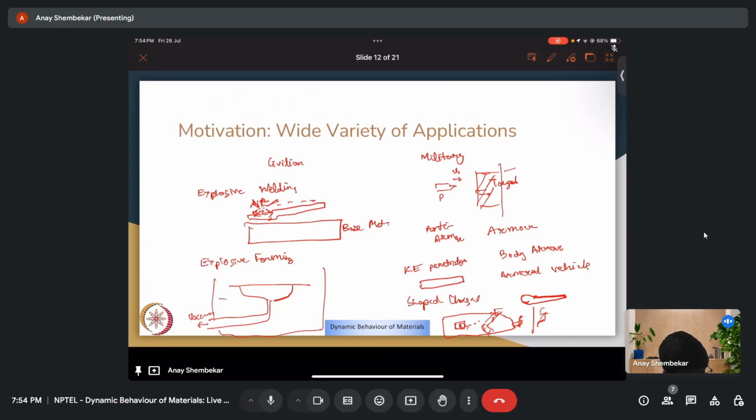You could have water or some other transfer medium for shock transfer, and then on the top, at a little distance away, you have a high energy explosive being detonated. This would create shock waves, which would transfer through the medium, and this is my metal worksheet, which basically gets formed according to my die.